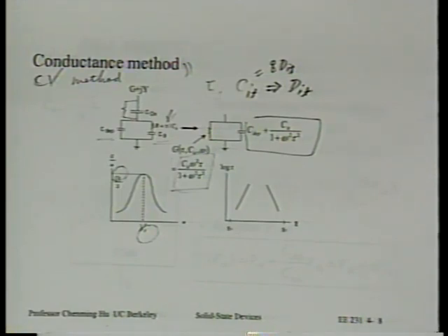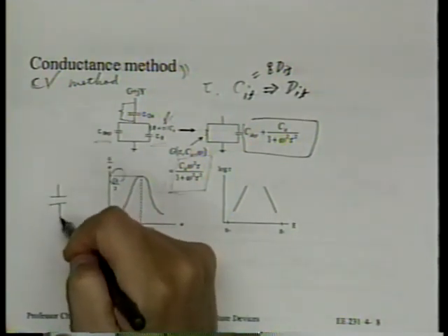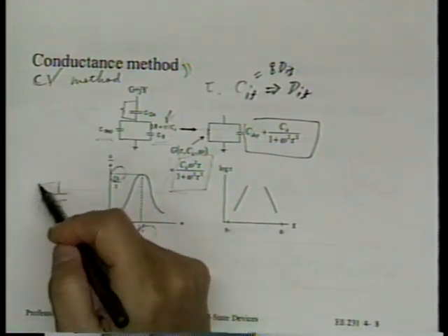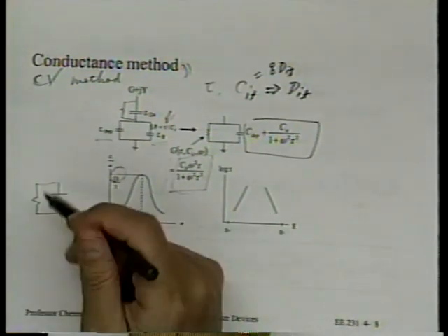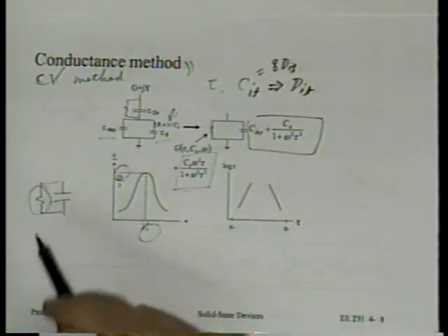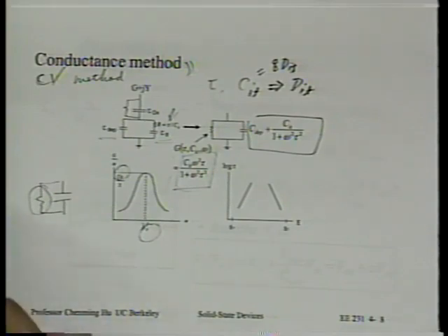Right now, one technique that's proposed to measure the dielectric thickness, not interface traps, just measure the dielectric thickness in the face of leakage, is actually to use multiple frequency. Try to model just the dielectric itself, not the interface, with a very complex RC equivalent circuit. You see, we don't even know with a new dielectric if we can assume this to be independent of frequency. You know, maybe Frenkel-Poole kind of a hopping phenomenon. We're not even quite sure how to model the leakiness.